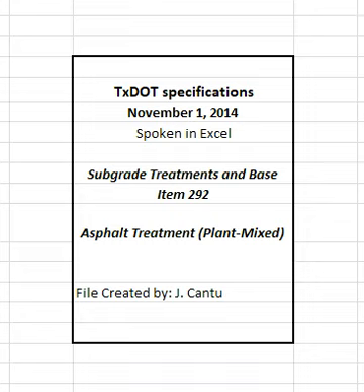4.5.1 Density control. Determine the number and type of rollers needed to obtain the required density. Operate the rollers in accordance with the requirements of this specification and as approved. Place and compact material to a minimum of 97% density as determined by TEX 126E or as shown on the plans. The engineer will determine laboratory molded density in accordance with TEX 126E from material sampled at the plant.